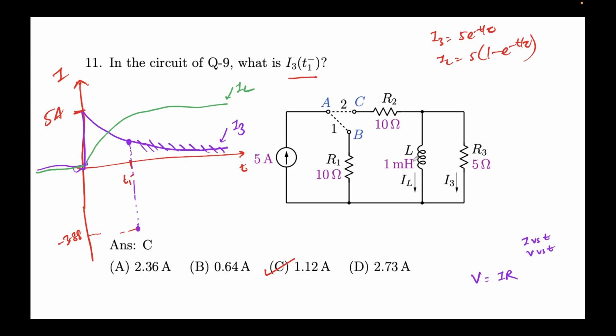These changes are happening due to the fact that usually when we change switches, you expect the current to change immediately, but inductance when coupled with resistances induces a delay, right? Effectively, this would have gone to 0, but that has not happened. Rather than immediately going to 0, it's slowly decaying. So inductors when coupled with resistors, or resistors and capacitors together, induce a delay. That's why these are called transients. This means they're taking some time to reach their steady state. For instance, if we would have allowed it for, let's say, 5 tau, where tau is the time constant, tau was 0.2.